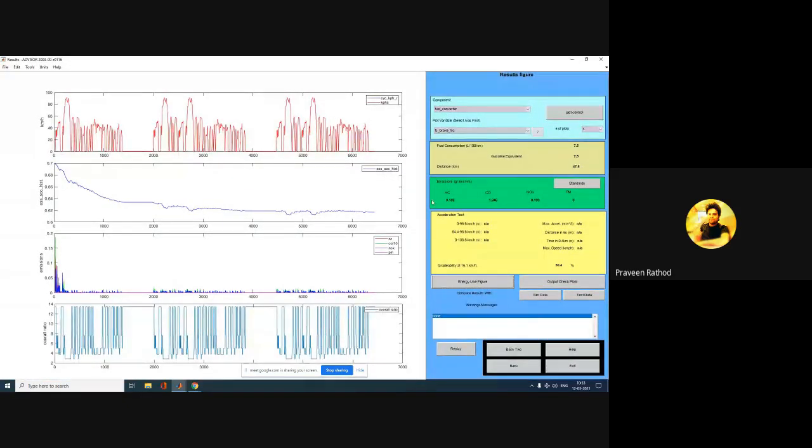And you can see the emission standards. Emission has been generated over here by seeing this graph. You can read out how much emission has been generated over here: carbon dioxide, NOx. If you want to see what the emission standards are, you can see. Nowadays BS 6 standard is going on in the market. If the emission standards increase in the future, say BS 6 to BS 8 comes, it is difficult to achieve by using a conventional vehicle, that is a petrol or diesel engine.